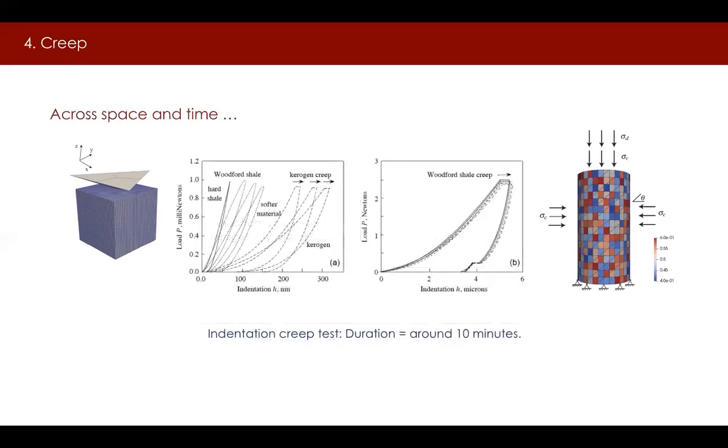We recall the standard loading protocol for indentation testing. First, the indenter is pushed into the surface of a sample. Then, the load is held fixed for several minutes before it is gradually removed. It is during this hold stage, under a condition of sustained load, where creep of the shale is observed.